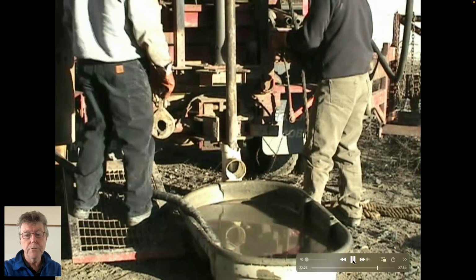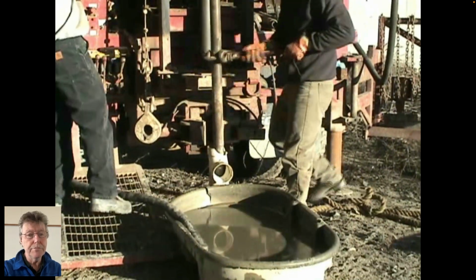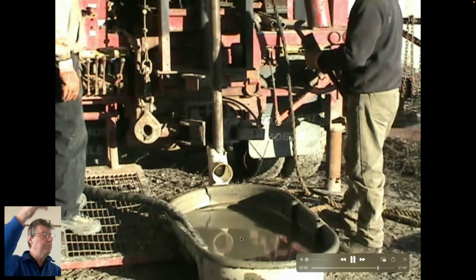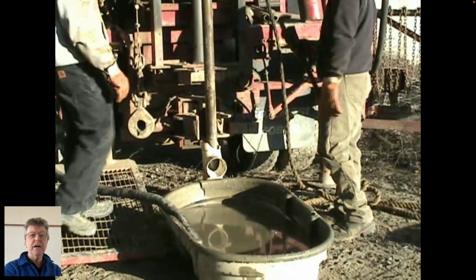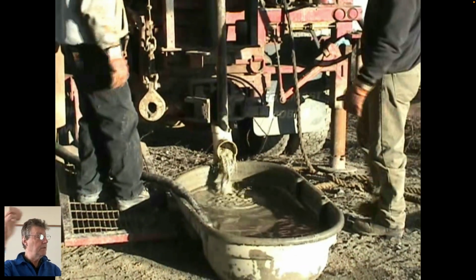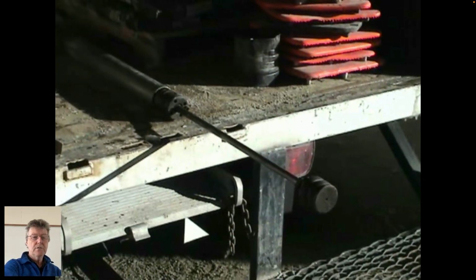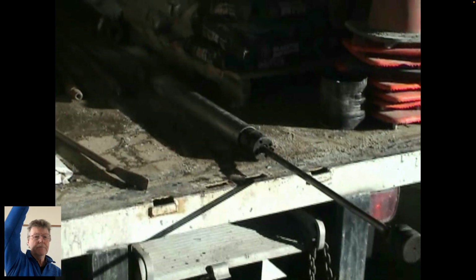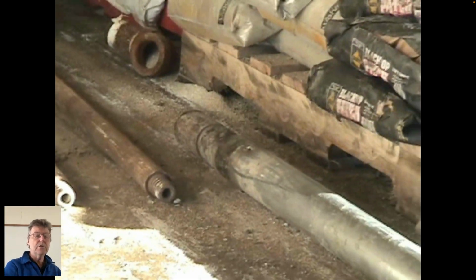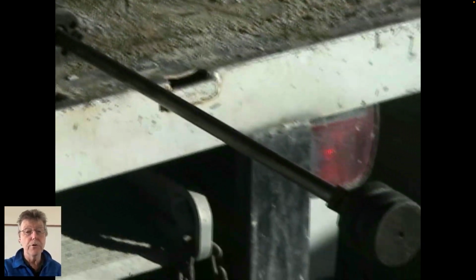And then you withdraw the sample. Pull up the drill pipe. You'd pull up each length of pipe, you'd clamp it at the bottom so it can't fall down the hole. You unscrew it, and then you lift it off in the mast, and then you bring the coupling down to the base, you tie it on, and then you lift up the next piece of drill pipe into the mast. You clamp it off at the bottom so it can't fall down, you unscrew it. So that's why you don't want to pull 100 feet of drill stem, because it's quite laborious.